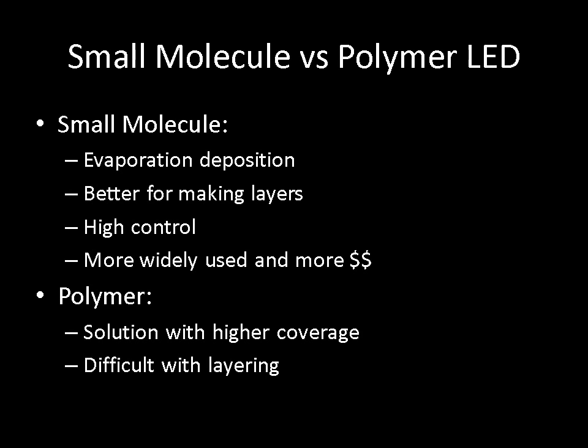There are two types of materials that can be used during OLED fabrication. The first type results in small molecule OLEDs, which use smaller molecules for the organic layer. Evaporation deposition is commonly used to deposit the organic material onto the emissive layer on the OLED. The second type, being polymer LEDs, use larger molecule solutions to fabricate the organic layer.